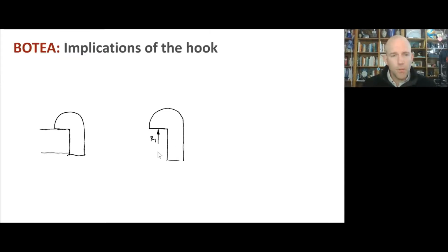So we've got this big upwards force. If we're going to have static equilibrium, we're going to need an equal and opposite downwards force on this component. And what we can see right away is we don't have static equilibrium. This thing wants to spin clockwise. So where we've cut the material down here, we're going to need a moment. So this bit of material is going to undergo bending.